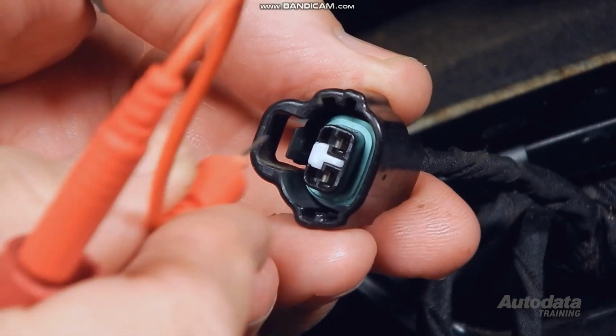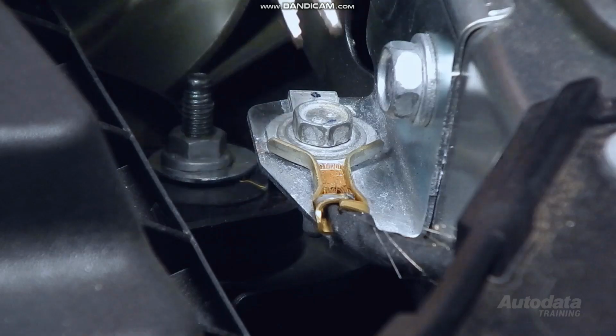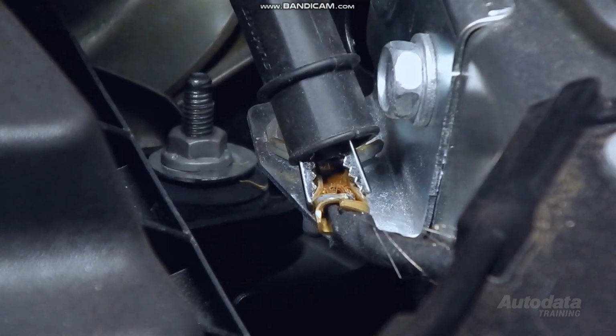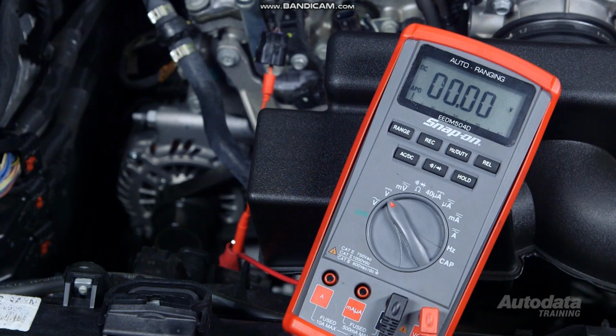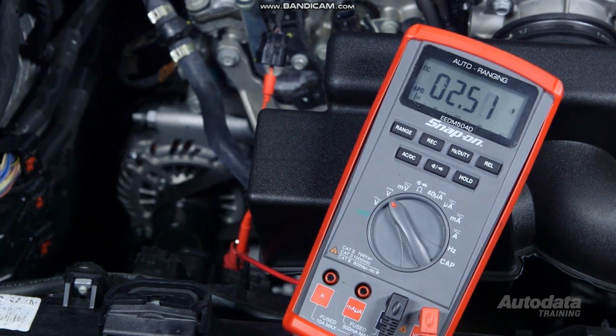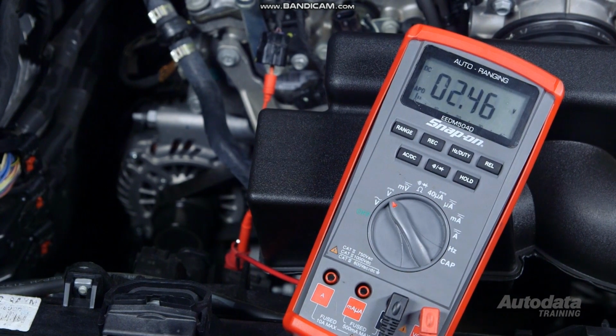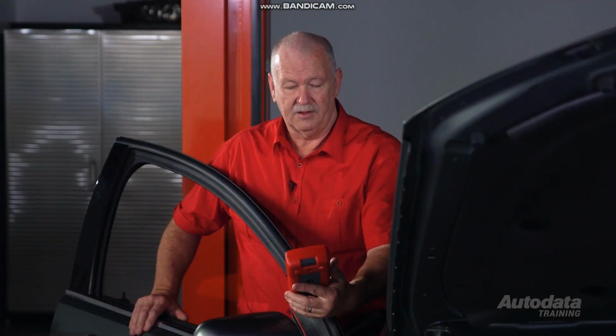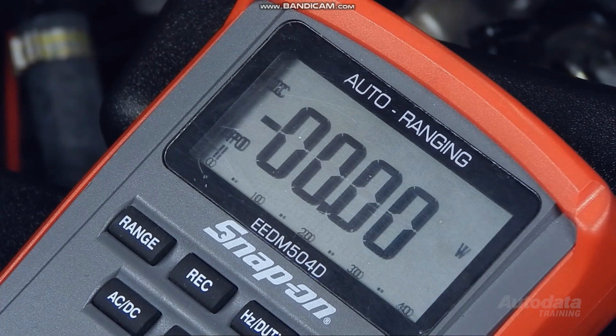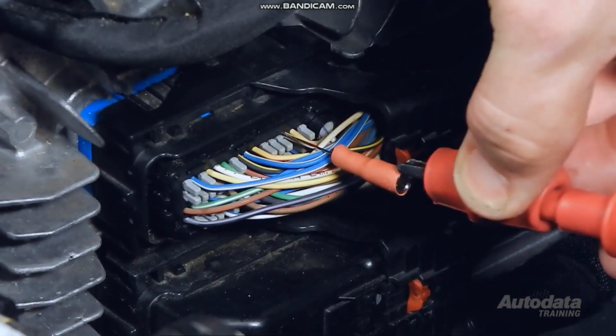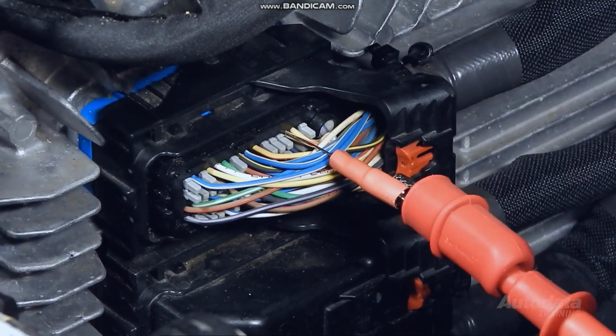Connect a multimeter to the actuator connector control terminal and battery negative. To get a reading, you'll need to trigger the actuator with the scan tool, if yours has this feature, or by starting the engine and increasing the RPM by quickly opening the throttle. You should see a voltage as you increase the RPM. If there is no voltage, then turn off the engine, back probe the module and retest.